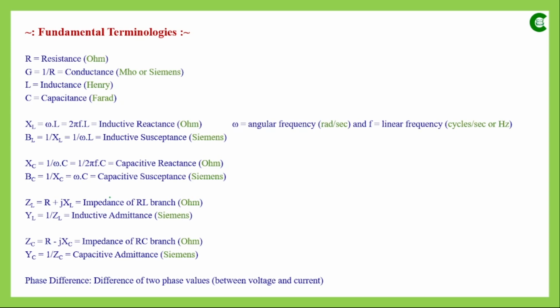So generally, when along with inductor we have resistor, we find out the impedance value of that RL branch or RC branch. And impedance does the same thing as resistance does, so it is again an opposition. The impedance is symbolically represented by capital Z. And again there are two types of impedances. So in case of RL circuit, that is represented or measured by R plus jXL.